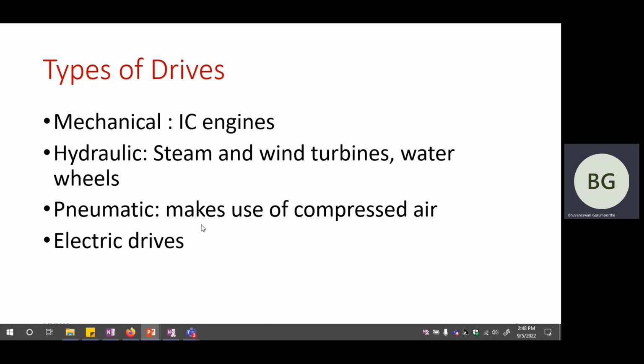Pneumatic drives are another type of mechanism where compressed air or compressed gas may be utilized, and when it is expanding, it is actually trying to drive a mechanism. So it is like a loaded spring. So when you have a spring which is loaded, when you allow it to slowly unwind, it drives a mechanism like olden days alarm clock. So it is very similar to that. The pneumatic controlled drives are basically operating with compressed air. So again, leakage could be an issue in this particular case because you are holding air at a very high pressure. So it's not going to be easy.